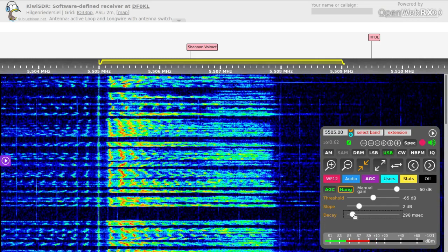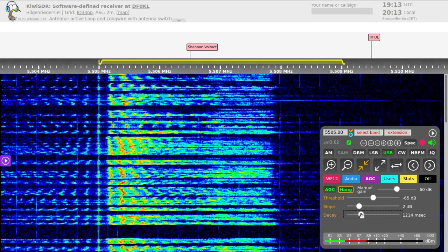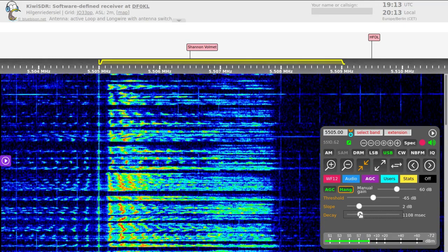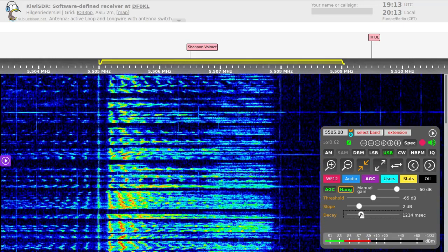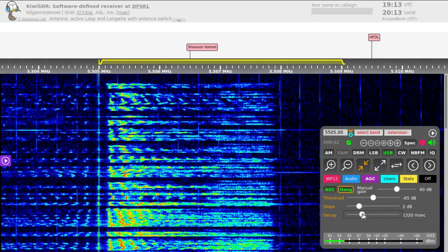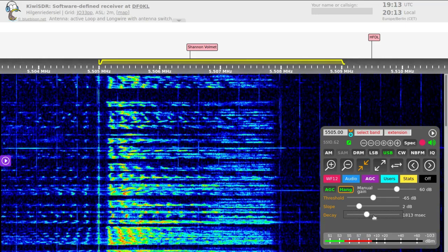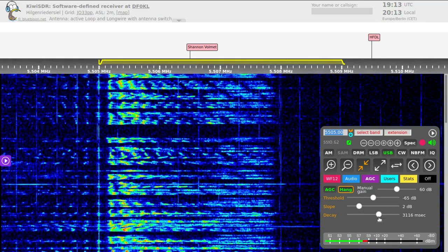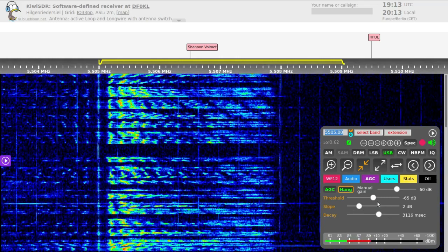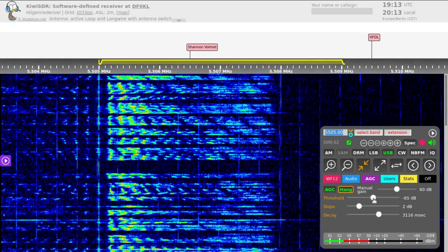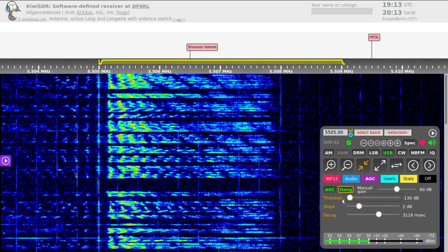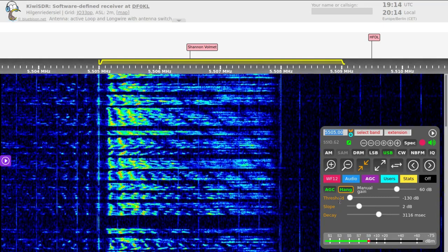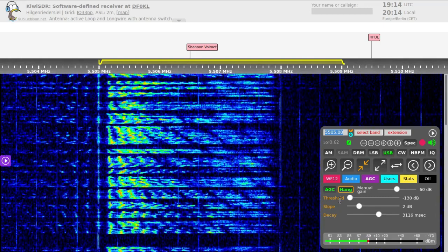Changing the decay time does not have much effect at this point. The gain is already reduced by the threshold setting. The only real effect for changing the decay time now is that if there's a very strong signal that comes up on frequency, or if the signal fades strong, then it'll protect your recording, cause you not to have much distortion.